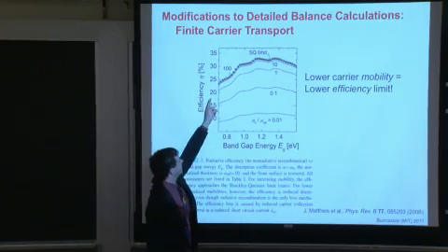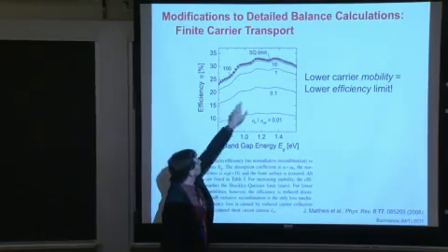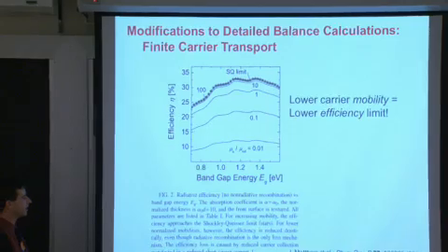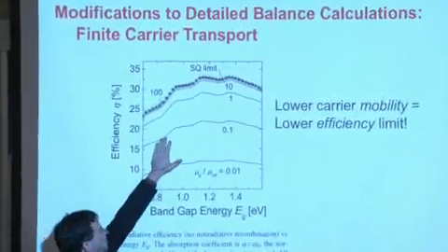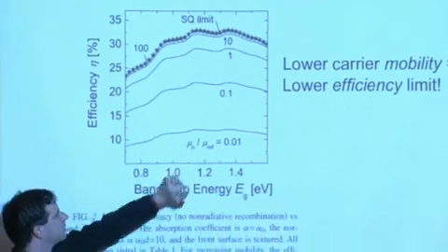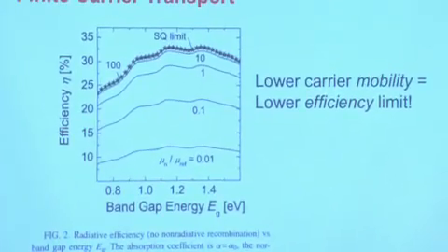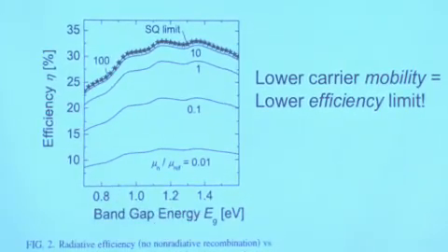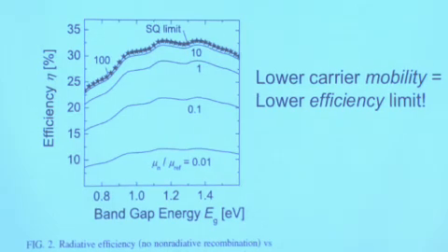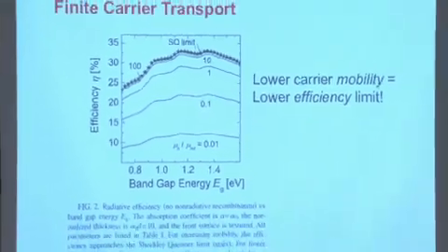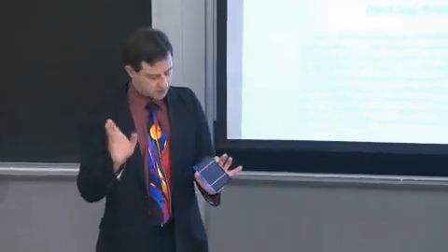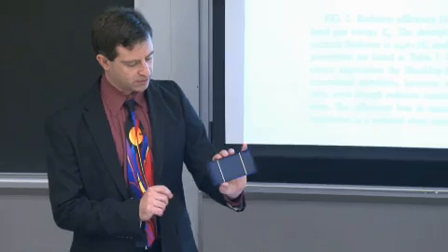And you can see, number 1, that curve that's starting here at the 20, that is for a mobility that is close to the optimal. If you drop by an order of magnitude or 2 orders of magnitude relative to the maximum mobility inside of a material, your performance begins to degrade considerably. And now you can understand why crystalline silicon, which has say electron or hole mobilities somewhere in the range of a few hundreds of centimeters squared per volt second. So keep that number in your mind, in the order of hundreds of centimeters squared per volt second hole mobility.